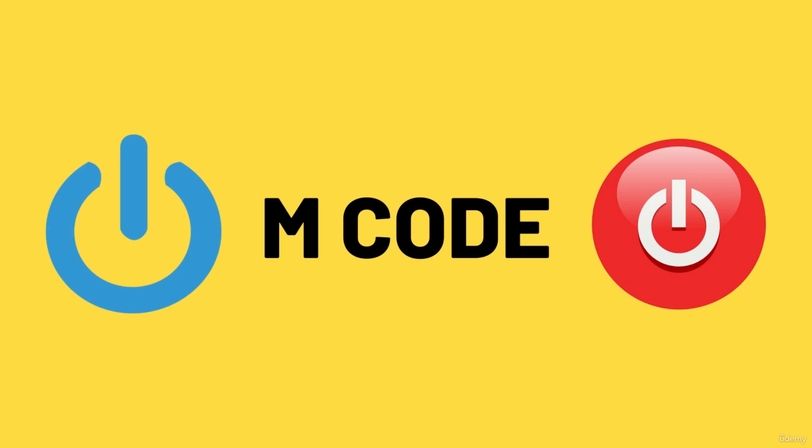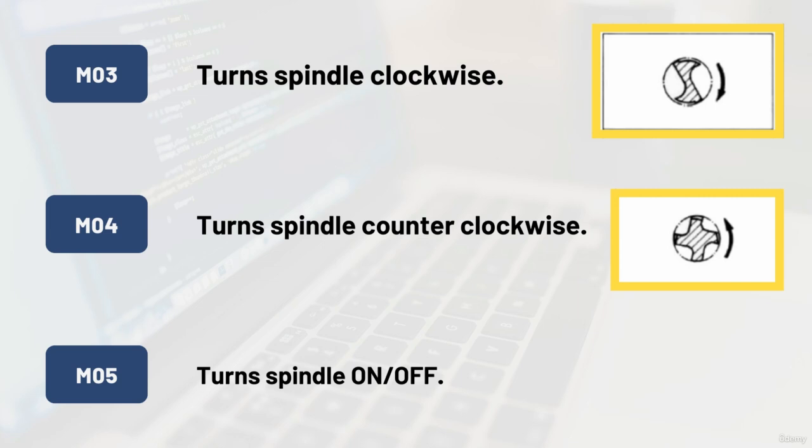M codes are not grouped in categories, although several codes may control the same type of operations, such as M03, M04, and M05, which control the machine tool spindle. M03 turns the spindle clockwise, M04 turns the spindle counterclockwise, and M05 turns the spindle off.